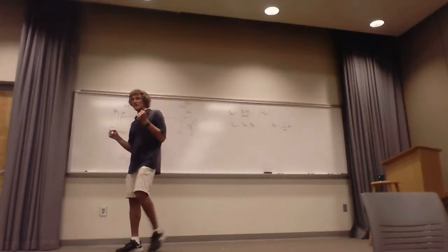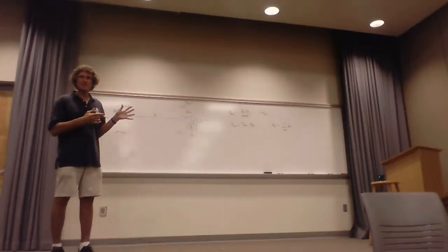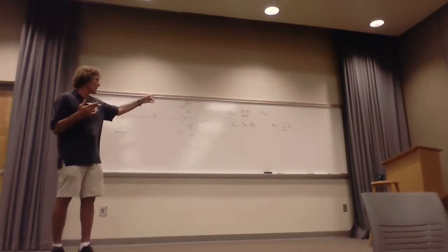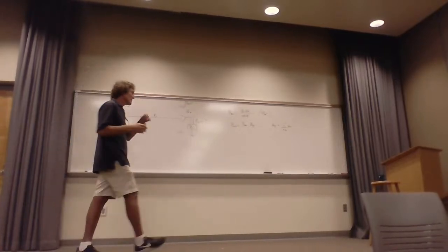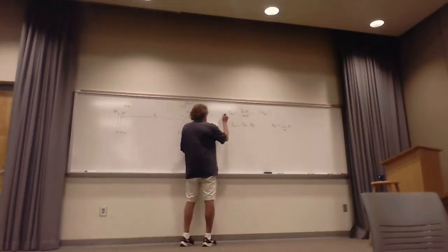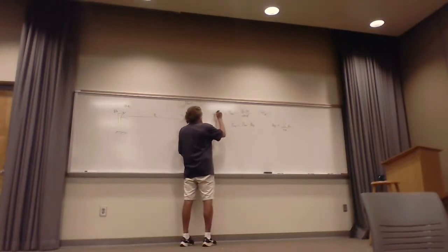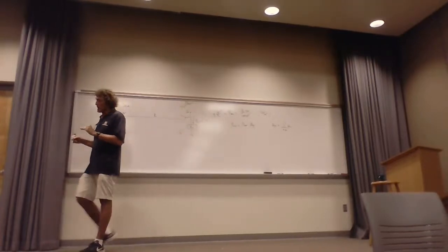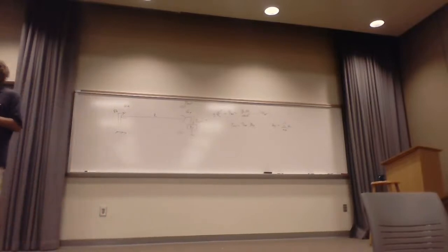The Friis equation comes out of that. I like to do it this way because that way, anything I want, you've got. If you've got the average power density, you've got the electric field at this point. That's equal to one half the magnitude of the E field squared over eta 0 at that point. You can calculate the electric field. Eta 0 is 120 pi ohms. You can get the H field if you have the E field, by dividing by eta 0.